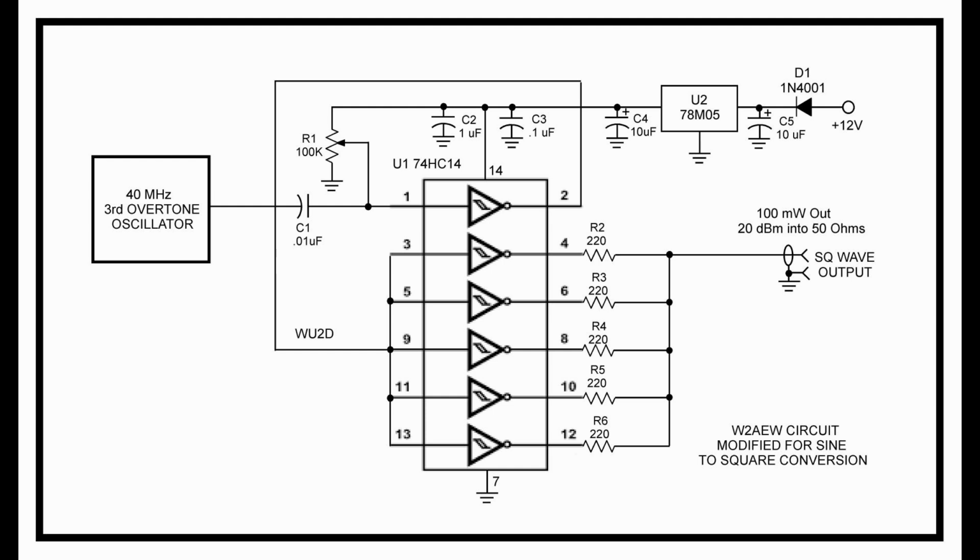We might even need to attenuate a little bit. But a square wave can be attenuated with no loss in high frequency performance, as long as the attenuator can handle the 5th to the 7th harmonic of the frequency. There's no loss going through an attenuator. Also, high-speed CMOS runs on 5 volts, so there's a small 5-volt regulator required to come off our 12 volts.